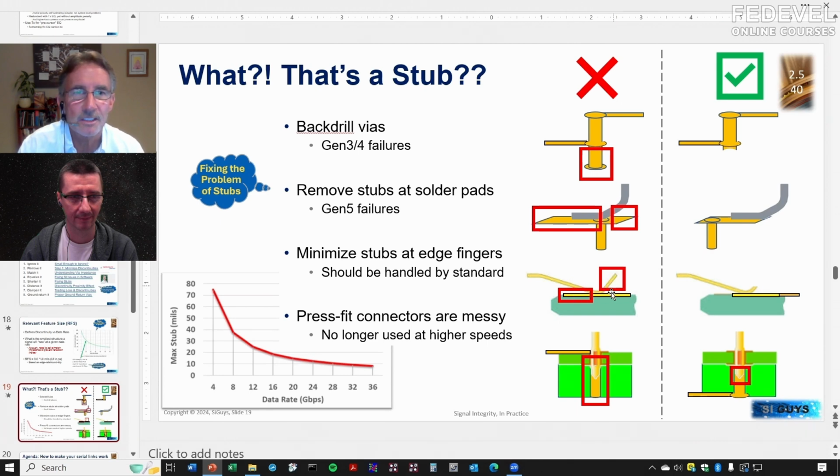And sadly, people still aren't thinking about this problem. I mean, look at this thing. These things that might be 60 mils sitting there, right? You got the signal trying to go through here. So this is the golden fingers or something. Yeah, this is the edge fingers right here. Okay, so that's a stub. That's a stub, right? So please, please, please, rest of the world, if we want to keep using edge fingers, we're going to have to mechanically get them more like this, right?